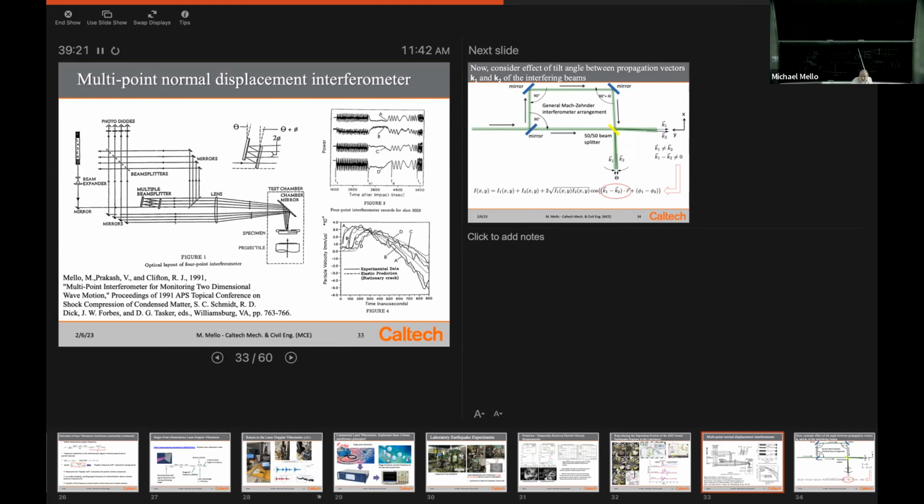The beauty of lab devices is you can see all the things, because it's not a box that's just spitting out an answer to you. This is what's recorded on the oscilloscope as something unique happens in this specimen. And then you study the rupture in that specimen. So this was studying a mode 1 rupture, this kind of a rupture. You can see the crack in the specimen in the little cartoon.